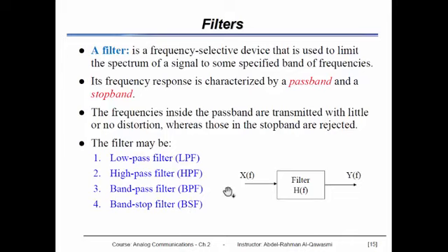So the use of the filter is based on the system that you are working with, but basically we use the low pass filter at the beginning of every system to eliminate any frequency higher than the baseband signal. The high pass filter can also be used for other purposes, to eliminate the low frequencies based on the information or message that you use.